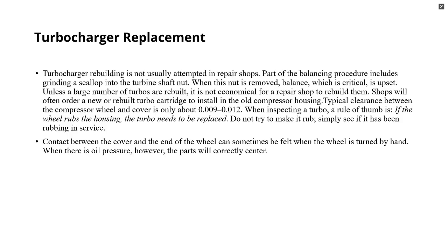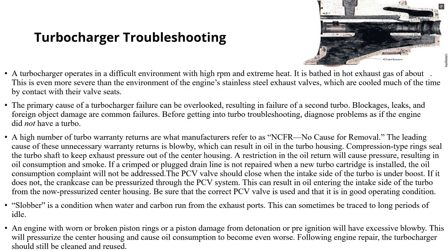Due to complexity, most turbos are replaced rather than rebuilt. Proper inspection can indicate if a turbo needs replacement, especially if there are signs of physical contact or damage. Common issues include blockages, oil contamination, and foreign object damage. Proper diagnostic steps can prevent unnecessary turbo replacements.